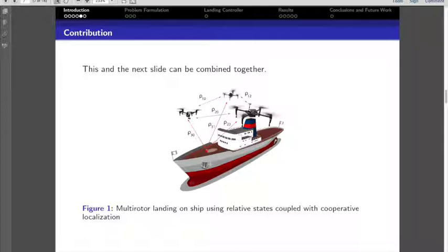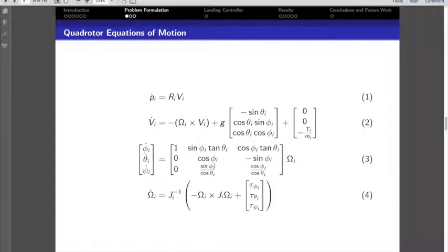Ship has an IMU as well, and that IMU you can use to get your velocity, both the linear and angular velocities. I will come to those when we talk about equations. And also you can get phi and theta, that is the attitude of the aircraft or the ship. Okay, so that is the idea here. So the equations of motion, maybe you can put a picture of a quadrotor and a ship and then show these phi, theta, psi, x's and all that stuff.